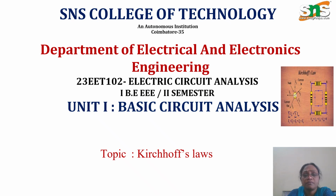And what is the difference between Ohm's law and Kirchhoff's law? Why do we go for Kirchhoff's law? Obviously, for a complex circuit, we cannot simply apply Ohm's law. That is, when there is more than one loop or more than one node, we apply Kirchhoff's current law and voltage law to find the voltage or current.